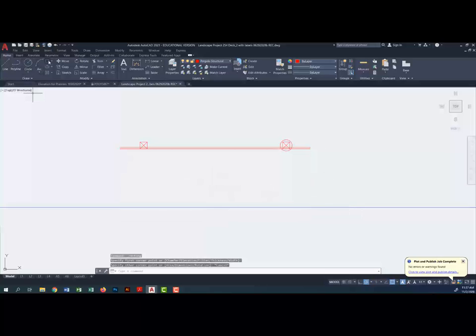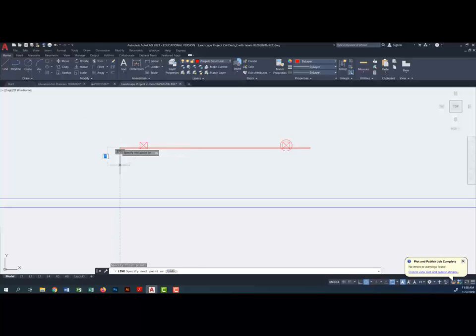And what I'm going to do is determine the height of the lintel. When I looked at my tables, my charts, they were 2x10s. So that's 9.25, and that's from here to here. And then the actual pergola lintel extends from there to there. So the end cut details I'm going to show at a later time.